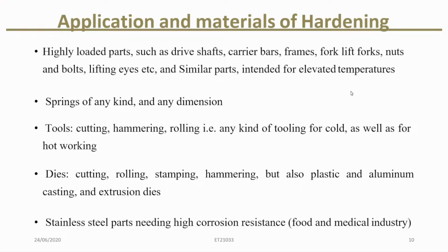Okay, when we discuss tools and dies, these are classic cutting tools, punches, chisels, rolling tools, plus hammering, casting, and extrusion dies. Okay, so these live by their surface. Hardening gives them the wear resistant skin they need.